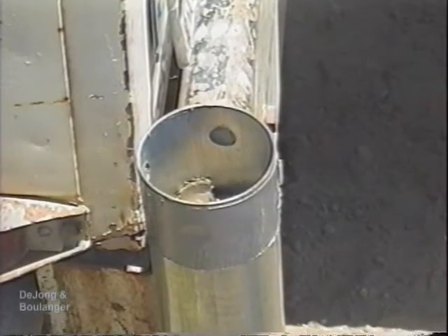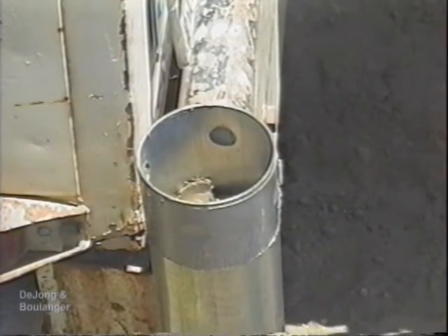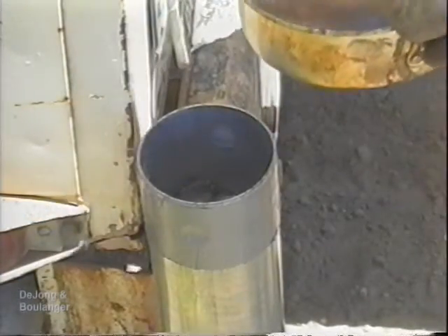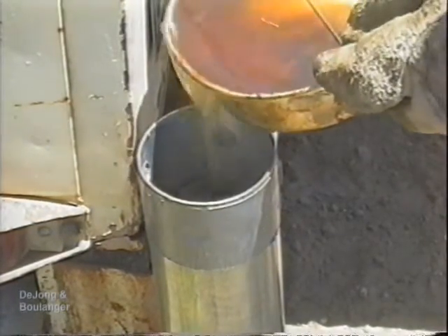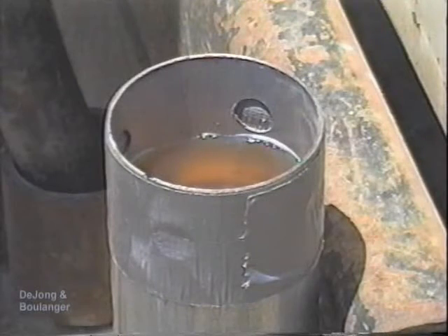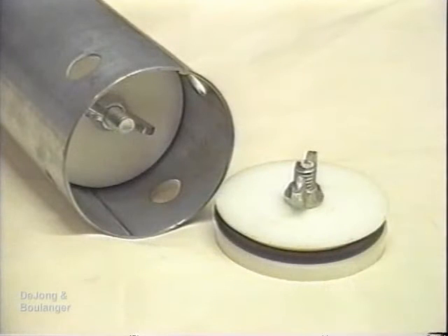Excess soil at each end of the sample tube is carefully cleaned away, and metal discs are inserted to protect the faces of the soil sample. Microfine wax is then commonly poured against the metal discs to form a seal. Alternatively, special O-ring packers may be inserted against the soil inside the ends of the tubes, and then expanded to form a seal. Tubes are then stored vertically in a padded box for transport to the lab.